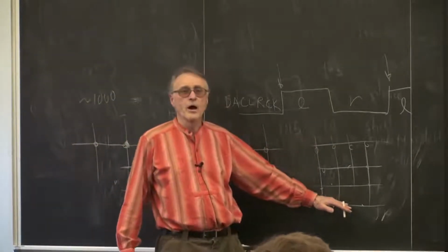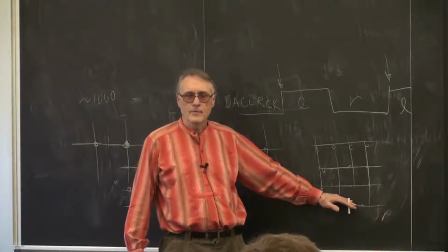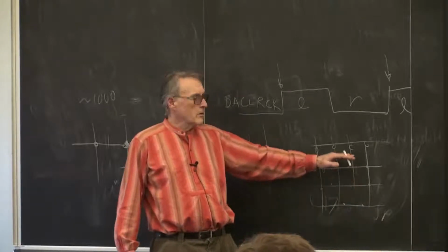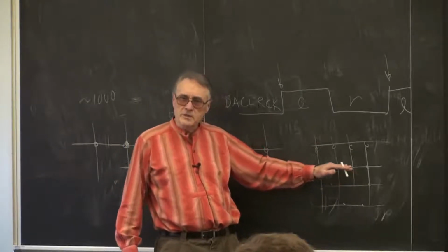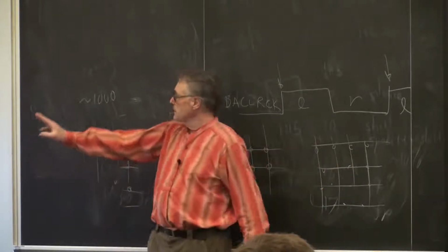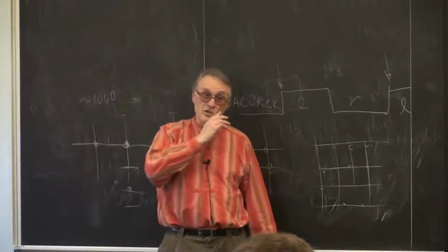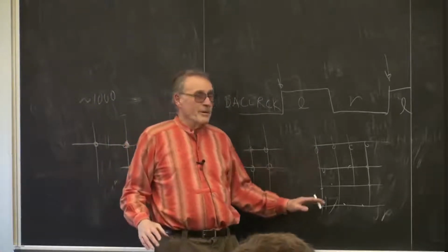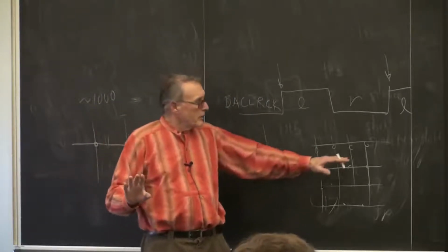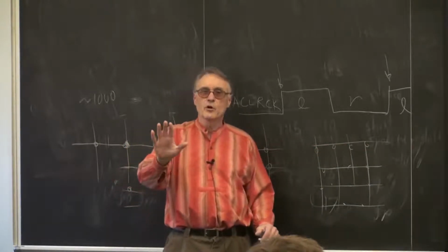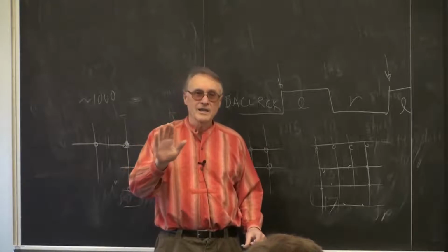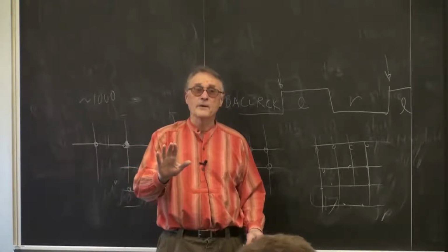what if we did 100 nodes on here? Well, maybe we're going to start running out of registers because it takes storage. It takes 2 words of state for each node. Maybe we're going to run out of memory, so maybe we should build one node block update state machine per M10K block, which is a memory block.